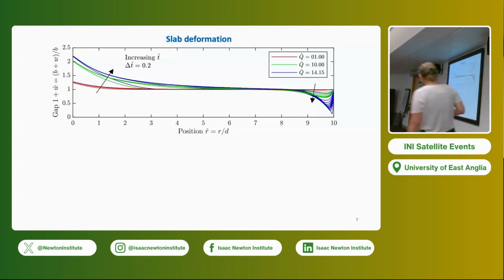And what I want you to notice is that essentially after a while, at least in cases of green and red data, we get to a steady solution, a steady profile in the shape of the cell gap. At the center, we have a bit of vertical displacement, but then for the majority of the cell, there is no displacement vertically. And then at the very edge of the cell, we have this bulging inwards towards the opposite wall that's at that level there.